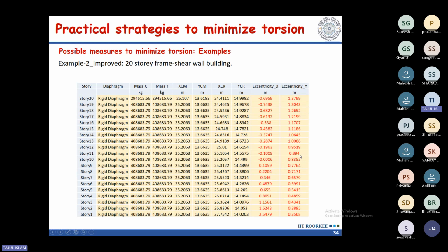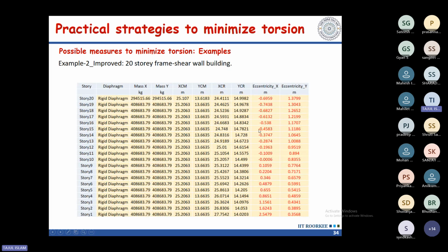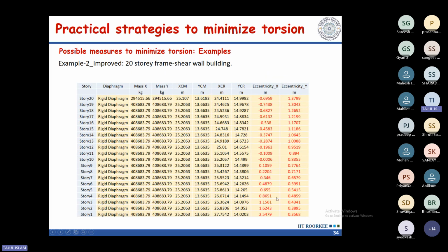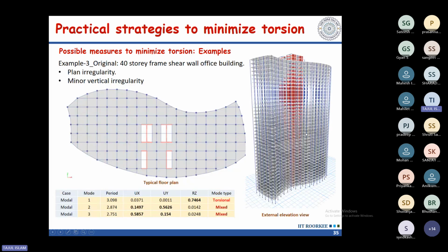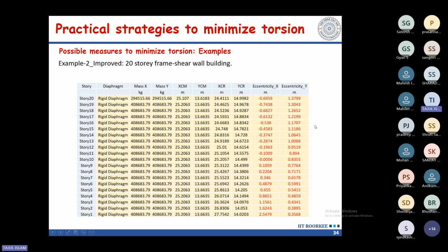which was not torsionally satisfied. So what I mean to say is, if you are relying on reducing the eccentricity parameter, you may not reach your final configuration at all, because this is not a reliable piece of information to check. Here you can see the torsional condition is satisfied, but the eccentricity condition is not satisfied. So you have to satisfy the torsional rotation condition and this modal response condition. The torsional rotation is theta, which I introduced earlier. So this was about the second example.